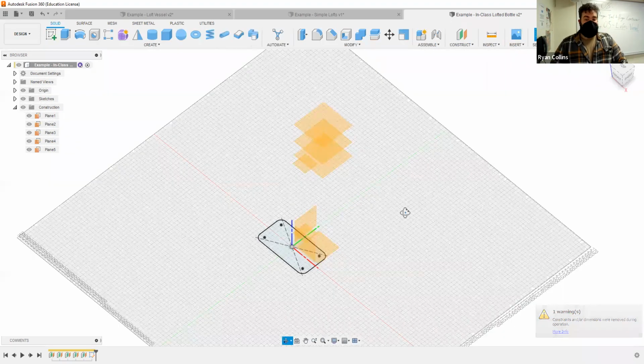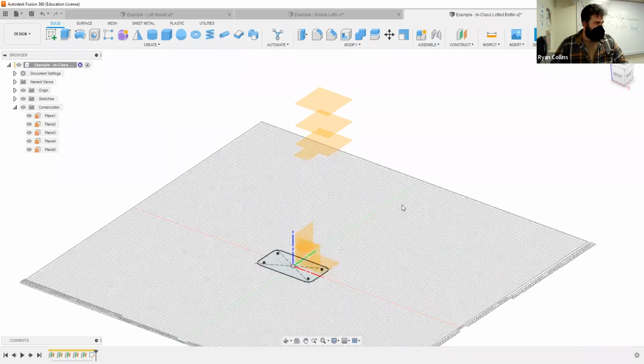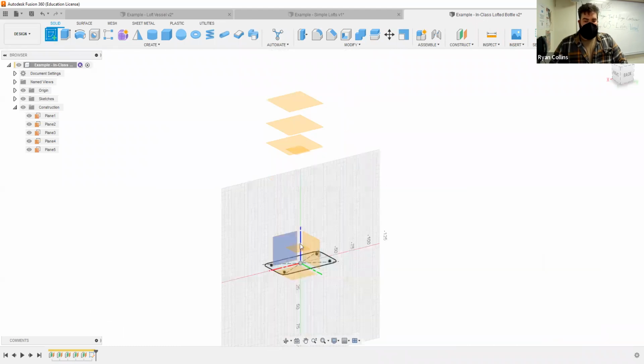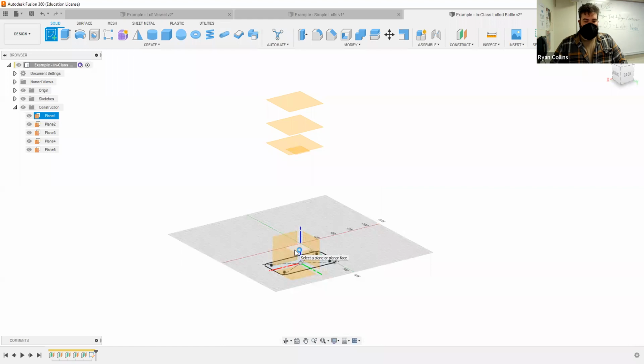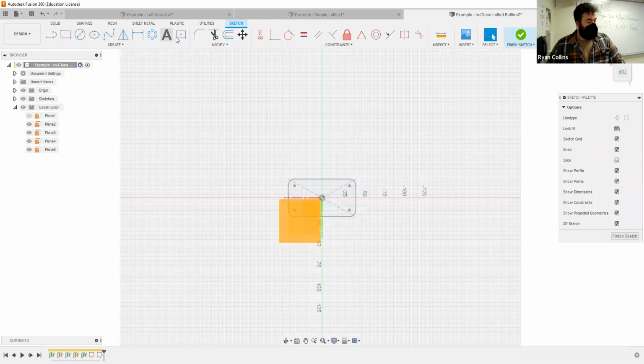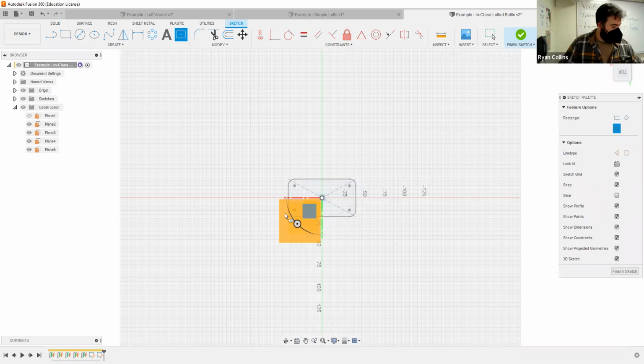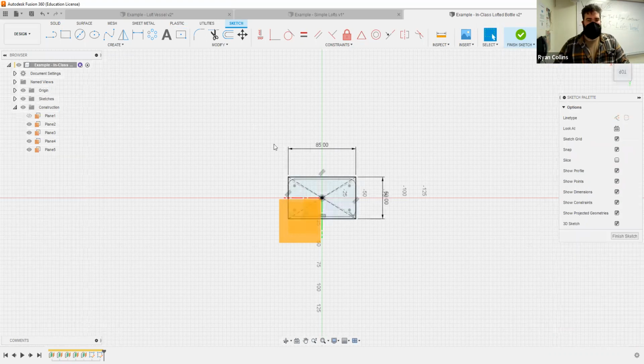So this is going to get really tedious at first, but it's repeating the same set of tools. Okay, next step. Create sketch. Next construction plane up. There we are. I want to do another center rectangle because that's what that one is, starting out. Now let's just say this is a little bit wider because it kind of is. So let's say it is 85 wide, but this one is 50 deep. Okay, great. And again, I'm just playing with the dimensions to give you all a better idea of how this stuff works.